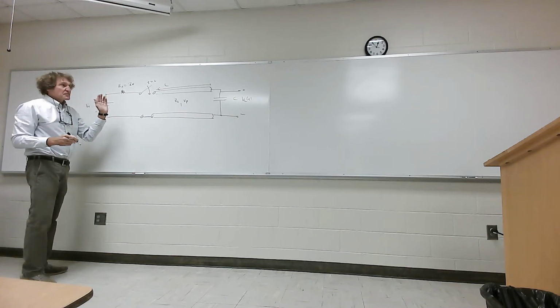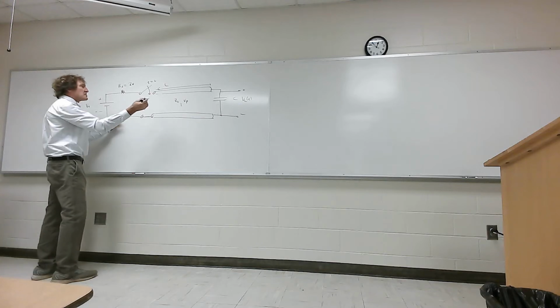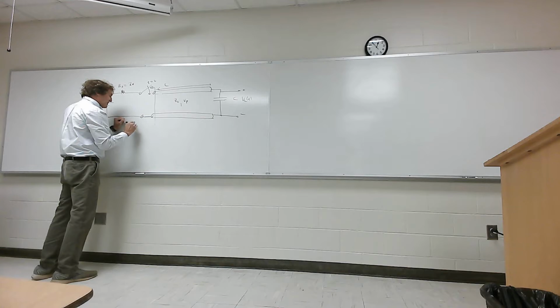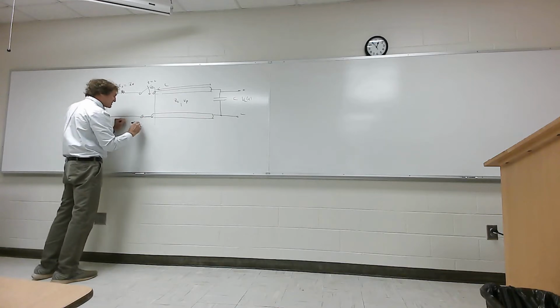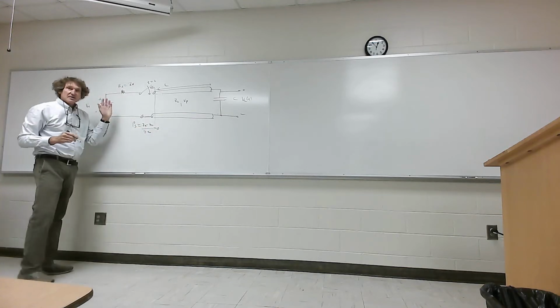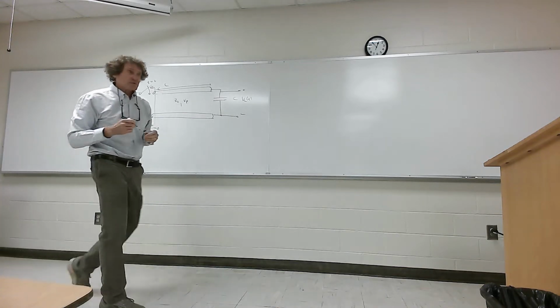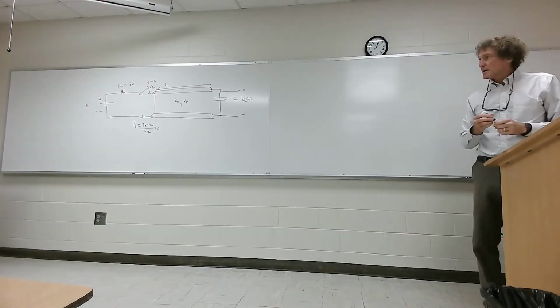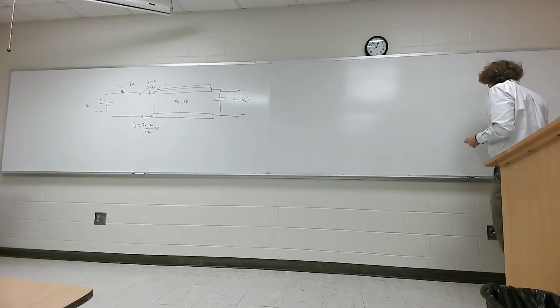So I'm going to go through this now. First thing I'm going to do is get the reflection coefficient on the source side, and that is Z0 minus Z0 over the sum 2Z0, which is 0, which is exactly what I want. I don't want any bounce from that source side. And that's more or less typical, from what I understand, in most logic circuits.